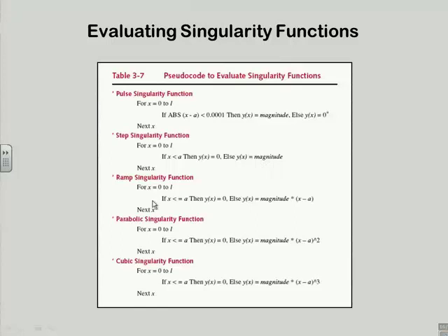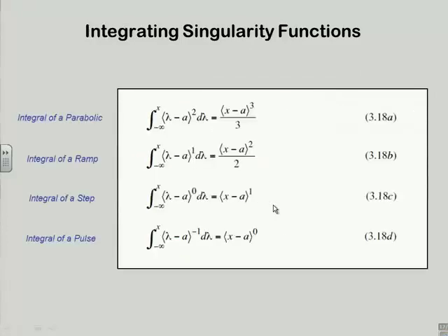And so forth. Ramp, same deal, except now it's going up like this. Parabolics going up like this, cubics going up like that. So to express their integrals, we have these expressions, and we're integrating from minus infinity to x in all cases. So that means that we're sort of off the beam at minus infinity, and I'm assuming x goes positive from left end of beam to right. Lambda is just a dummy integration variable standing in for x. So these expressions allow me to work those integrals.